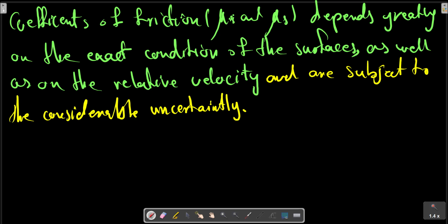Because of variability of the conditions governing the action of friction, in engineering practice it is frequently difficult to distinguish between a static and kinetic coefficient, especially in the region of transition between impending motion and motion. Well greased screws, for example, treated under mild load, often exhibit comparable frictional resistance whether they are on the verge of turning or whether they are in motion.